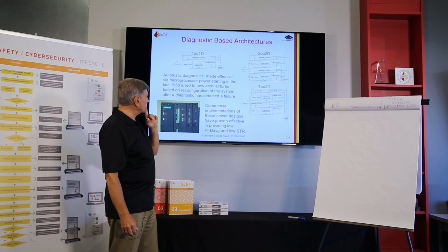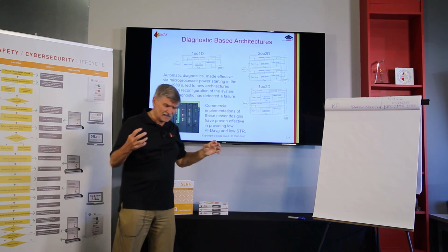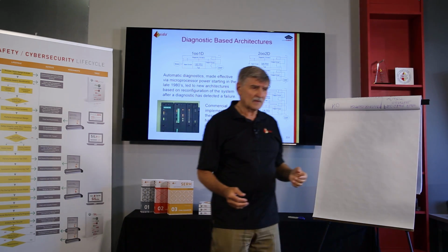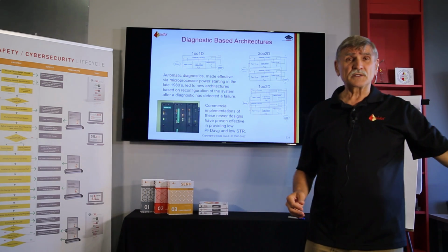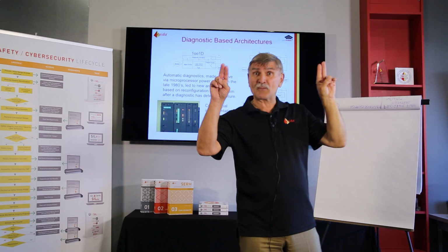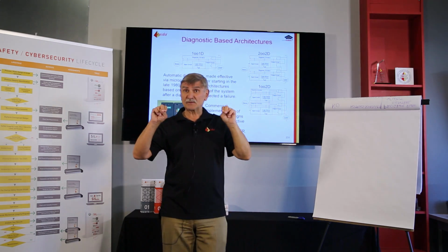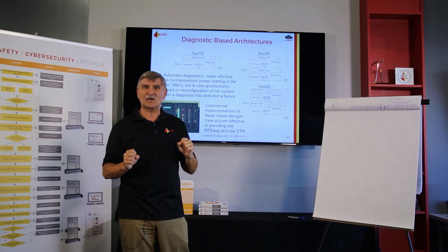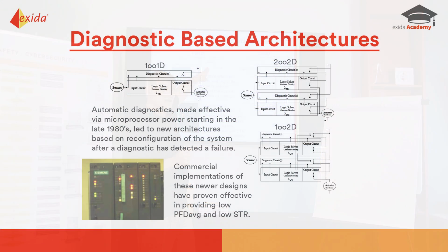Now that was interesting. In fact, in the early days of using PLCs for safety, many engineers thought of the idea of putting in a watchdog timer. Maybe you still see some designs today that use this external watchdog timer. That was a D. The logic solver would send a pulse up to this timer.